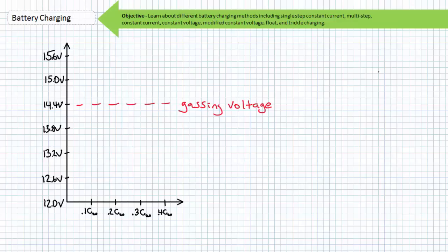As previously stated, one of the hard upper limits imposed on batteries is that of the gassing voltage. The gassing voltage is the voltage at which electrolysis begins and water is electrically split into its gaseous constituents, oxygen and hydrogen, both flammable gases that must be vented. A certain amount of gassing is expected and actually serves to circulate the electrolyte. However, excessive gassing depletes the electrolyte and changes its chemical concentration.